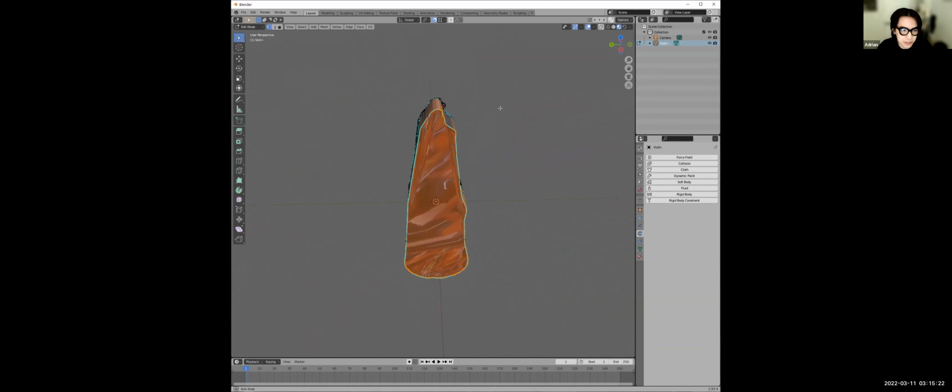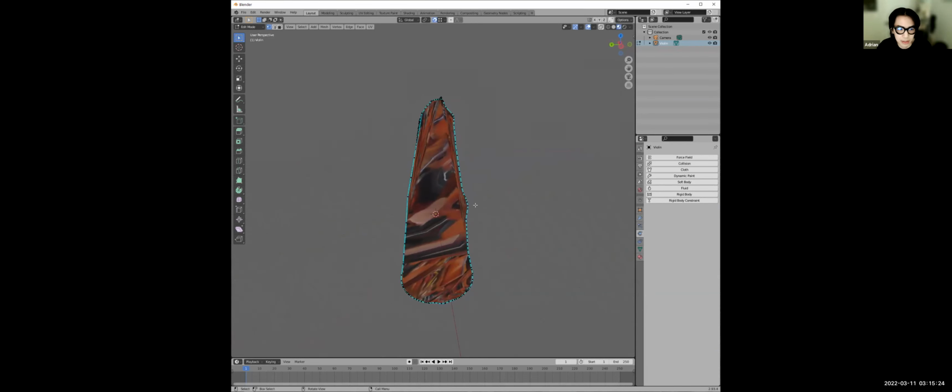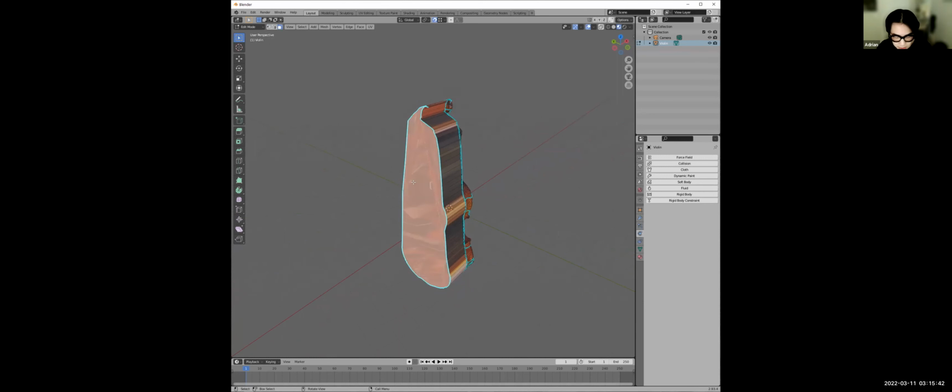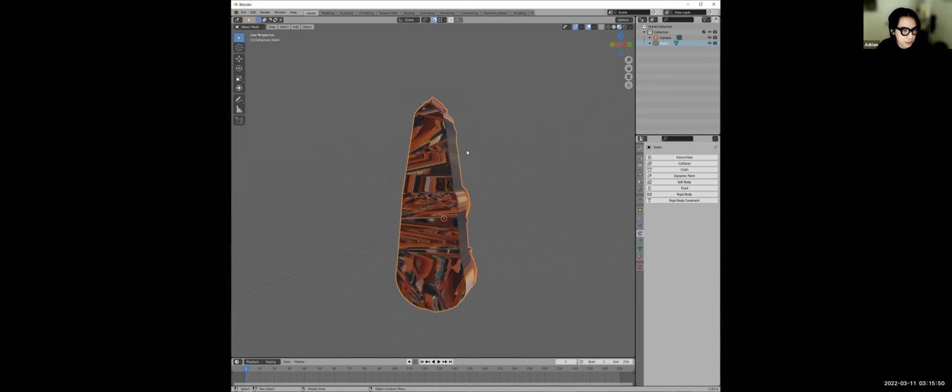And the very last thing we need to do is we need to break up the surface so that it properly inflates. It just needs to be triangulated. So up in the top here, you've got these 3 buttons. This one's got a point, this one's got a vertex, this one's got a face. Hit the face one, and then just so that you can select faces, select this face, right click, what was it? Triangulate faces right here. So we're just going to triangulate that, and then we should be good.